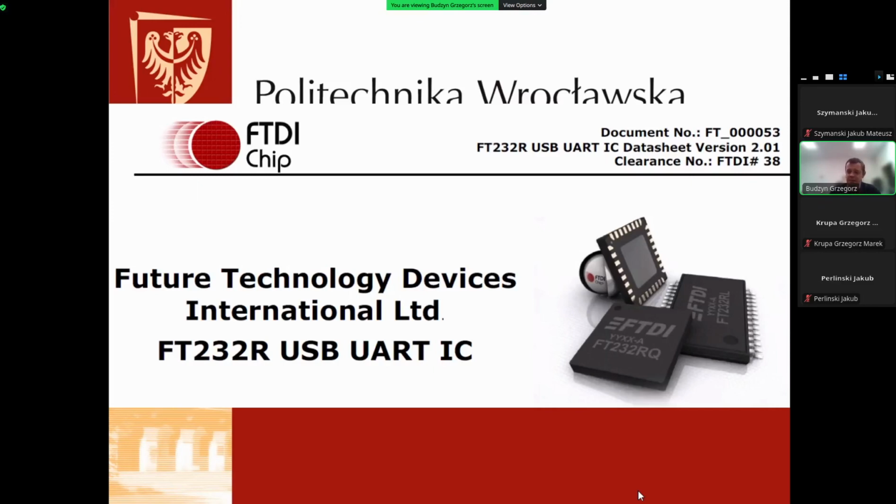But the USB, as you have already noticed, probably, hopefully, last week, is significantly more complex. Although we need fewer cables, just 2 cables, the complexity is shifted from the hardware, which was the case in UART with these RTS, CTS, DTR lines, so with hardware flow control, to the software, where we have not only software flow control, but also types of traffic, and also node addressing, and in general a network layer, not only a link layer, but also an application layer above this.